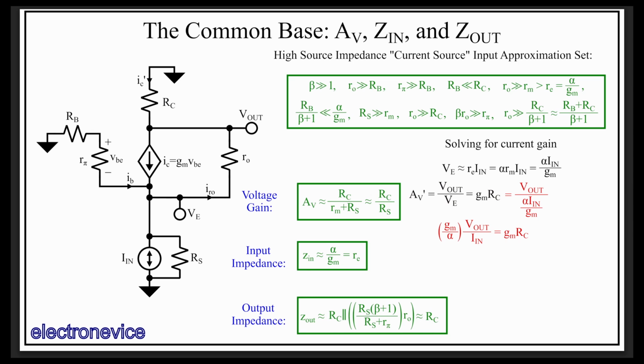Well, one more important point about current gain is that similar to making the source resistance very high on the input side, we have to short circuit the output to ground to get the short circuit output current. So this necessarily modifies our gain equation by effectively adding RL back in parallel with RC. If we then assume that we make RL very small, or approach 0, then we can conclude that all the current flows through RL, and that RC parallel RL is approximately equal to RL.